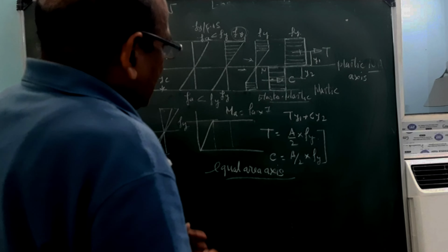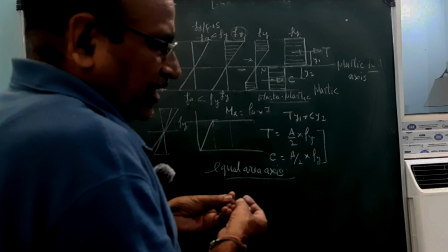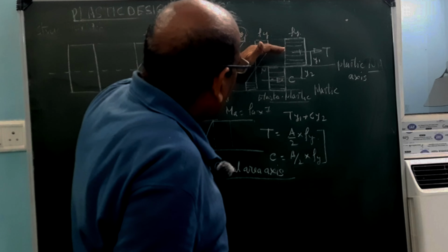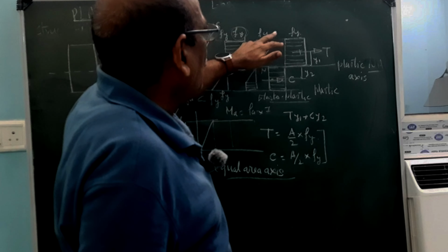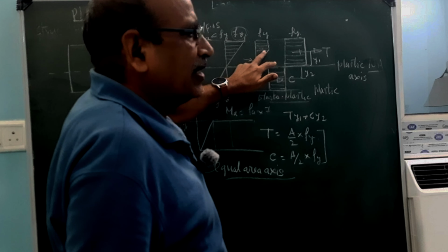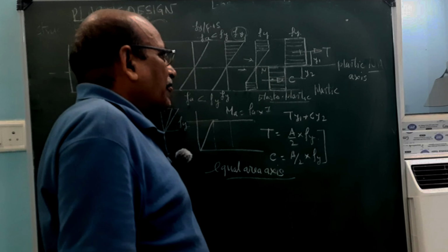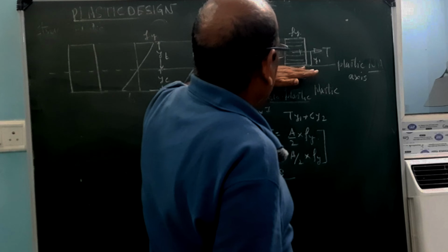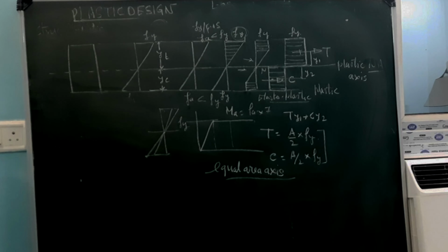If you increase the deformation at constant stress, then the lower fiber will get stress up to Fy, and slightly all the layers from this part will take up, and this will create a plastic axis, and a plastic hinge will be created.